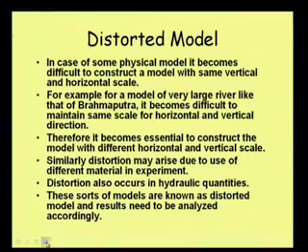But there may be a situation, suppose we are trying to develop a physical model of a very big river or maybe a harbor. Then the width of the river is very large, or the horizontal extent of the entire model is very large. Then to have it in a smaller model, we may have to reduce the horizontal scale too much. Say we can make the horizontal scale 1:100, and then we are getting a model. But the depth of flow, then we will have to reduce.